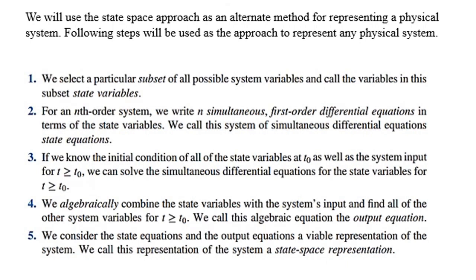Dear students, with the help of state space, we can represent dynamics of a physical system in time domain. For this representation, some steps are followed as discussed below. For state space representation, first of all we will identify all the dynamic variables which give sufficient information about the system at any instant of time. And these variables will be termed as state variables.